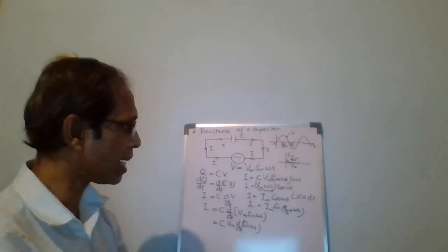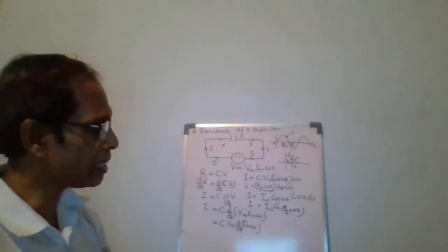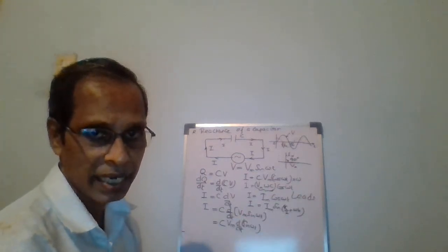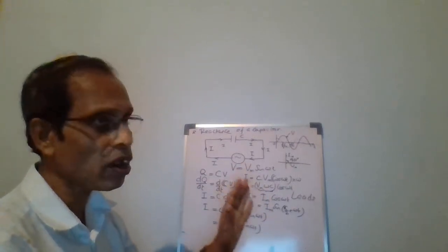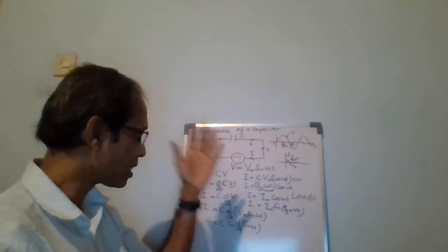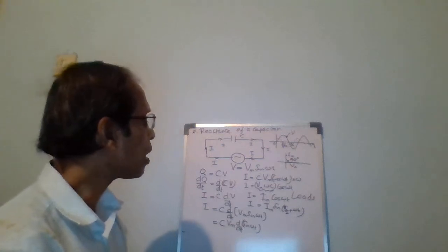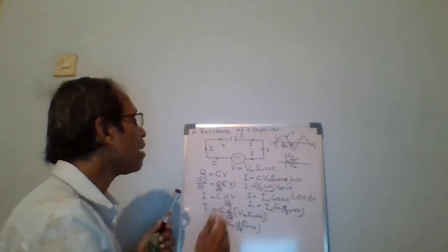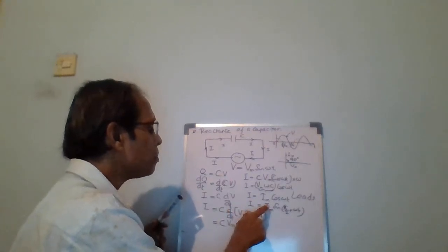Sometimes we call this 90 degrees angle the leading phase angle. Always we say whether current is leading or not voltage. Here in a capacitor, current is always leading voltage. Now we have V is equal to Vm sin omega t, I is equal to Im sin omega t.